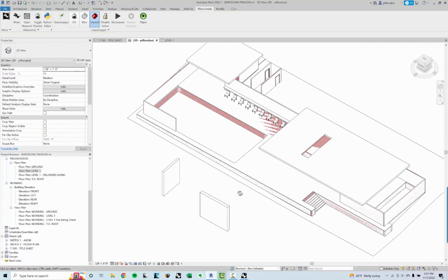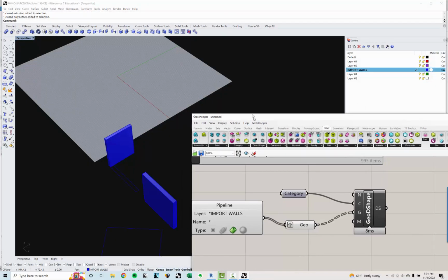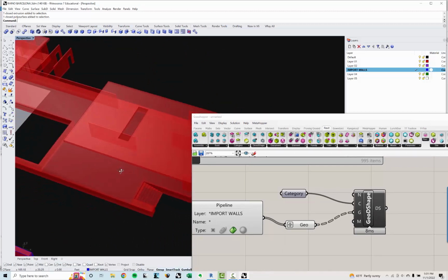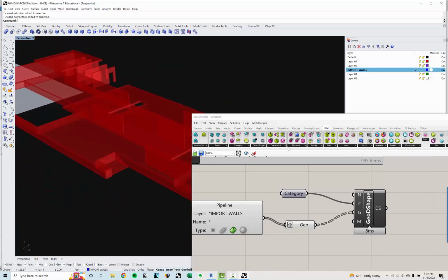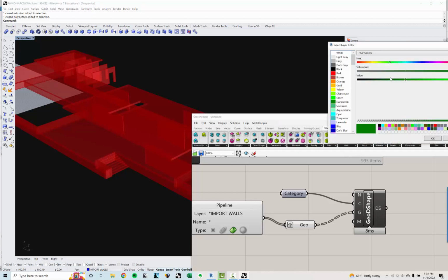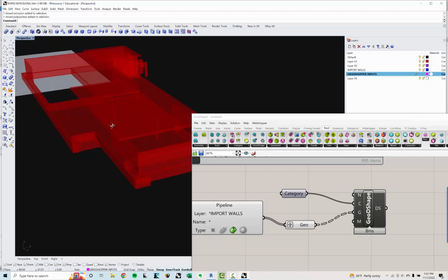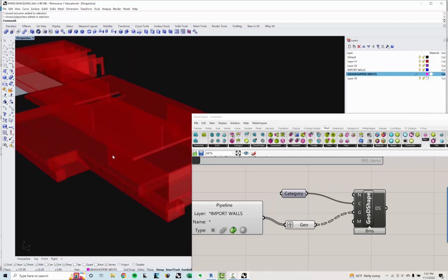So that's the real quick way of doing that. Now the last thing is I may want to do something a little bit more complex here in Grasshopper, and to give you guys just a little bit of an insight into some basic Grasshopper stuff, what if we wanted to panelize a wall here in the Barcelona Pavilion? So I'm going to set up a Grasshopper inputs layer. I usually like to make Grasshopper inputs magenta. That's kind of my standard. And I could bake these geometries to make them more accurate, but I'm just going to eyeball it for now.